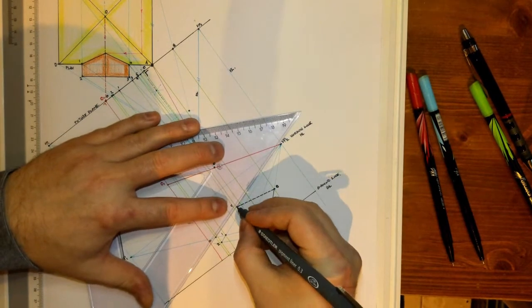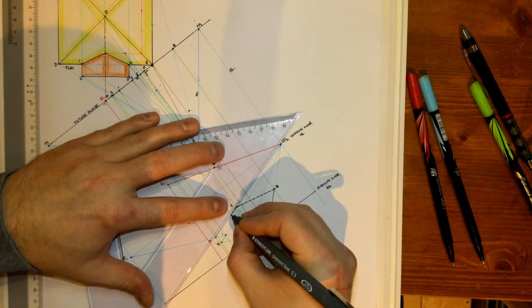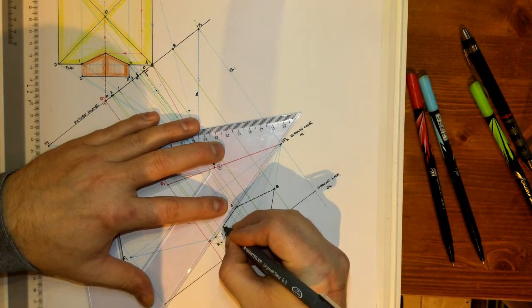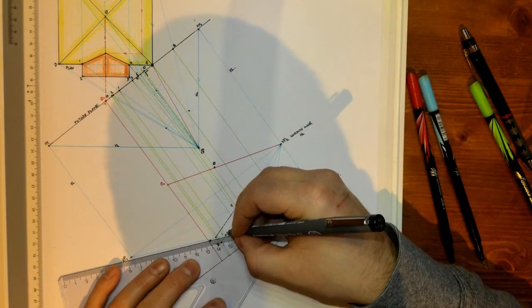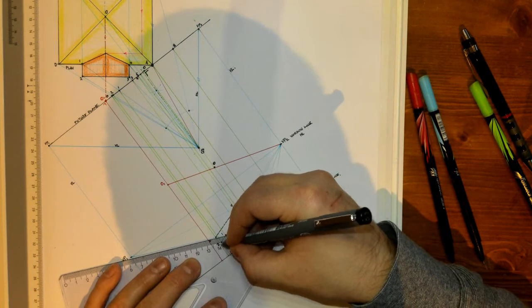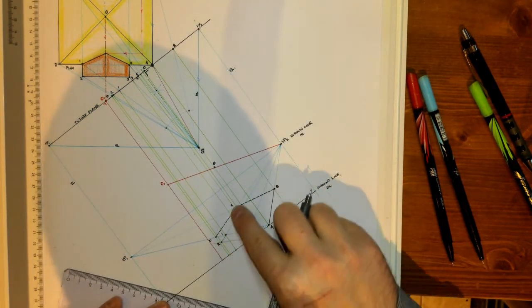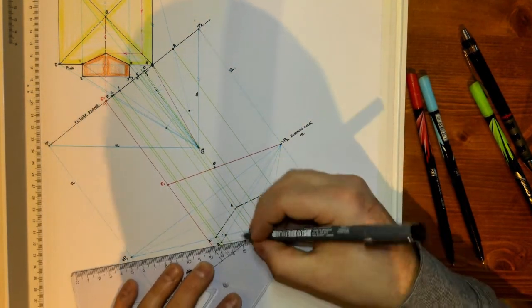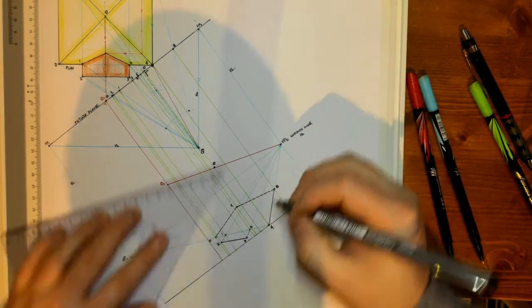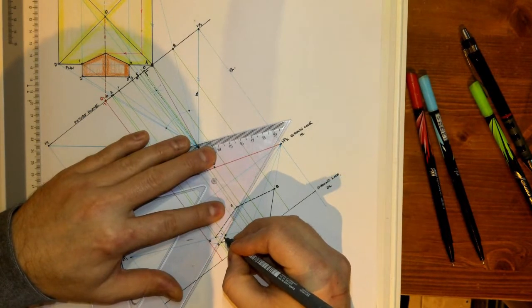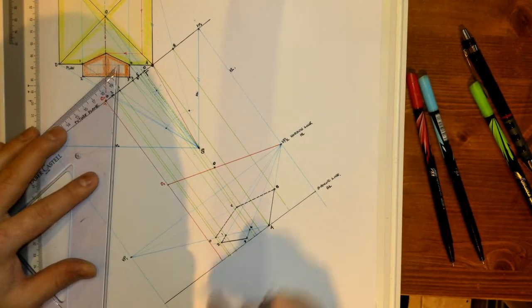Likewise, the line C to D, that's going to be a hidden detail line. We do have another bit to draw up in the front here, so I'm not going to heavy in that bit. I will heavy in here, and I will heavy this bit here. Well, that will be a broken line there as well.